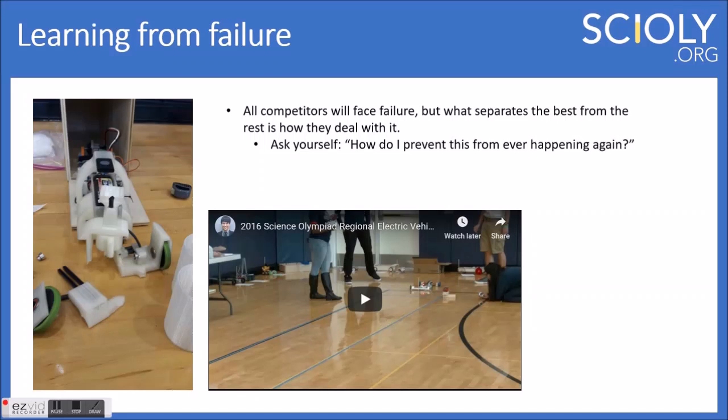We did have a couple things that we improved. We made sure the encoder was having better contact. We made sure to check that very often to make sure that belt wasn't slipping. I believe we also glued a few of those parts in place with epoxy, and we reprinted that front piece to be a bit more sturdy, have more contact. I think we filleted a couple parts so we smoothed the corners, because having a 90-degree angle corner is not very strong compared to a smooth fillet. So there's a couple things that we did to improve that.